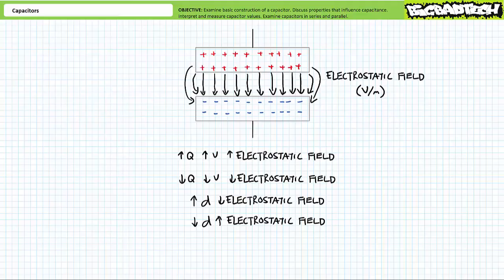First, the electrostatic field in units of volts per meter places an upper limit of voltage that can be safely applied across any capacitor. If the electrostatic field ever exceeded the breakdown strength of the insulating material inside the gap, whatever is inside the gap can become a conductor and bridge the two plates. Accompanying this breakdown event is a large arc of current which equalizes the charge, often destroying the device in the process. As such, capacitors often state a maximum safe working voltage under which the capacitor will function as intended, and above which catastrophically, sometimes explosively fail.